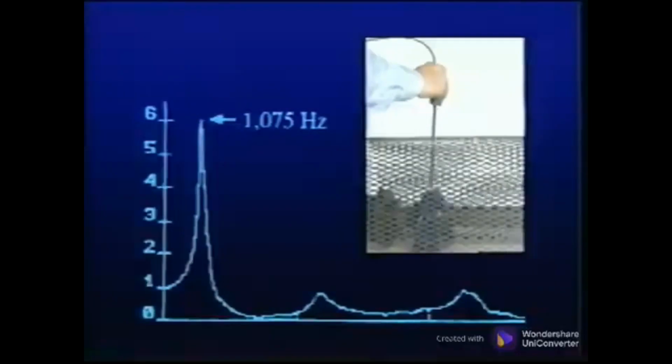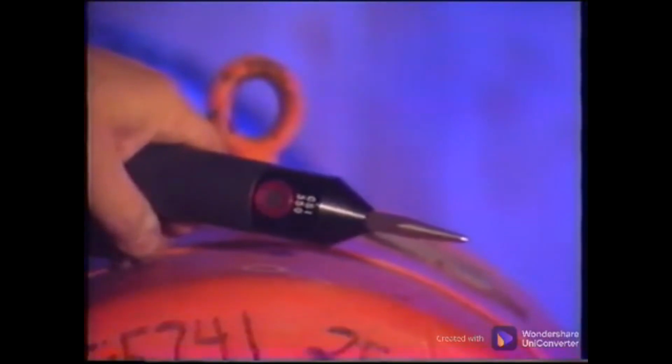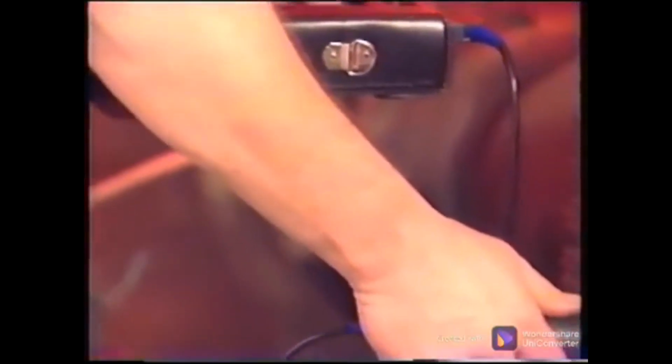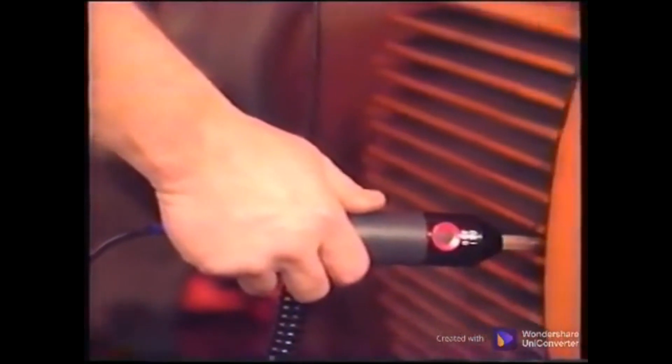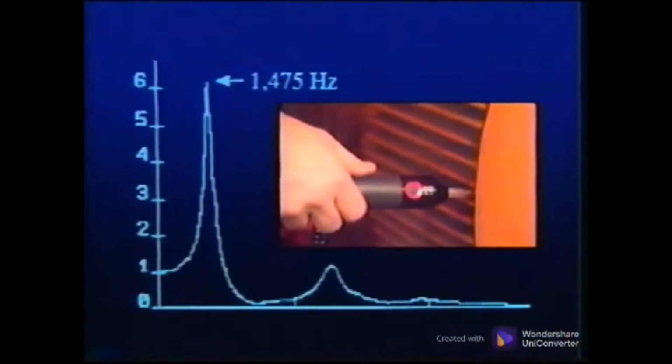This 2-inch stinger is also a very handy tool and may be part of the standard accessory kit with your analyzer. It is handy because it allows places to be reached that could not be accessed with a magnet or other mount. The linear range of the sensor with this 2-inch probe is approximately 500 Hz. This would be suitable for many machines that have shaft turning speeds ranging from 1,000 RPM to 1,800 RPM.